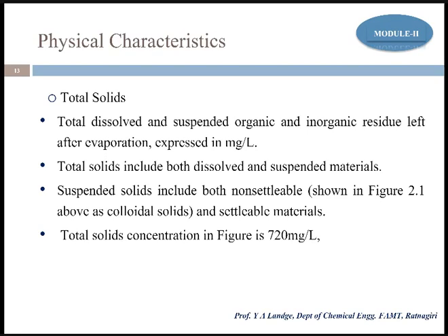Though we cannot see it, the solids are present, and with the help of an instrument we always check before choosing which type of filter we need to place in our home. We always check the TDS, the dissolved solids and their range, and on that basis we decide whether to go for RO, the reverse osmosis membrane filter technology, so that the excess TDS present in the water can be filtered out, so that it will not harm the human body.